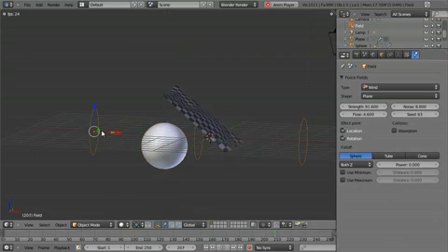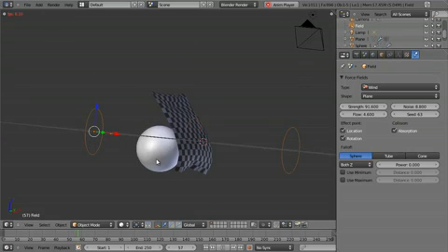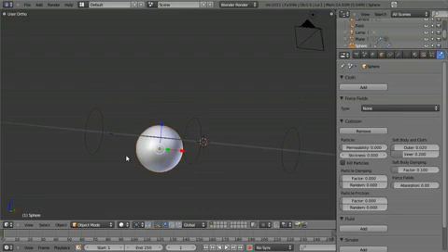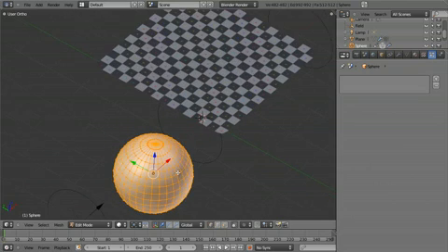And what we want to do is on our effector, change the collision to absorption. So now collision objects will block out the wind. Now you'll notice this has pretty much killed my simulation time, but if we were to go back to the beginning here, well, this is too slow to actually demo here while recording, but what it does is allow this wind to be blocked by our collision objects. And one of the reasons this is taking so long is that, as far as collision objects go, this is fairly complex.